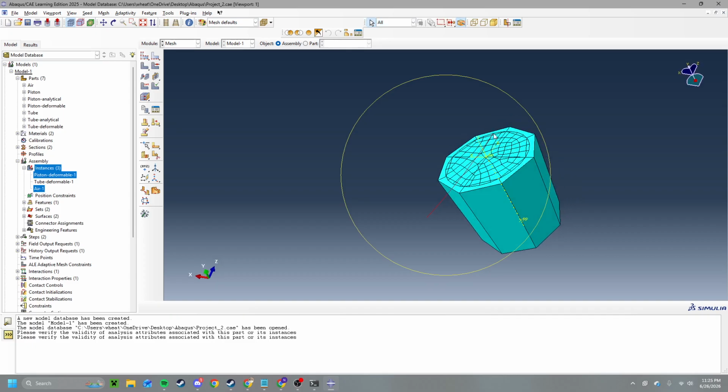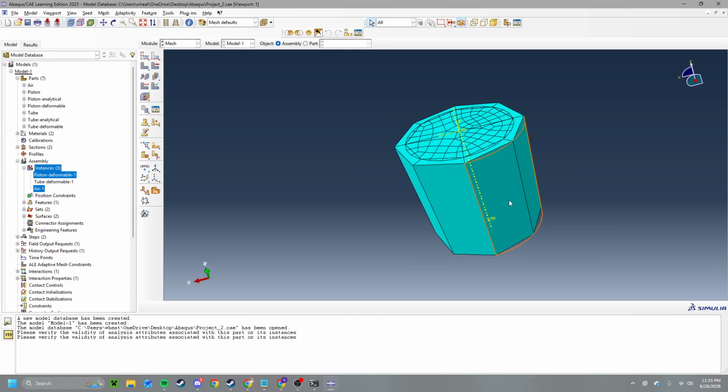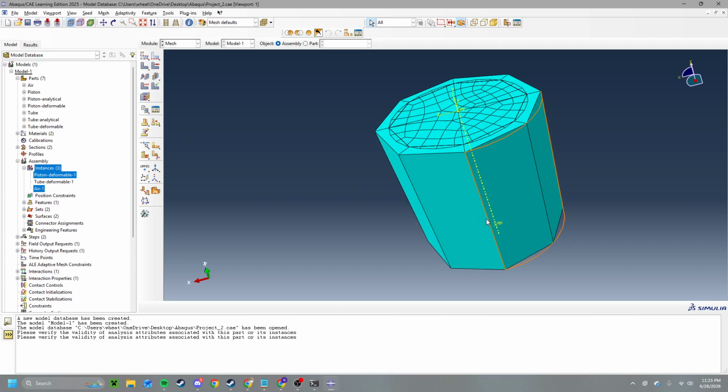For my mesh, I'm using the education edition, so I'm limited to 1,000. With the interactions between Eulerian and Lagrangian, which is the typical solid components that we're used to, it works better, I've seen, if the Lagrangian components are larger components. Ideally, you want the Lagrangian components to be larger than your largest Eulerian component element. That'll help it model these boundaries more correctly.